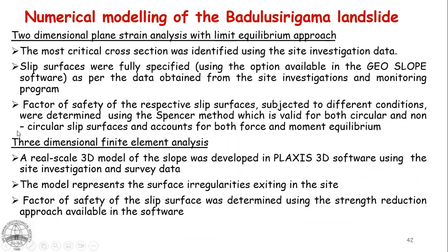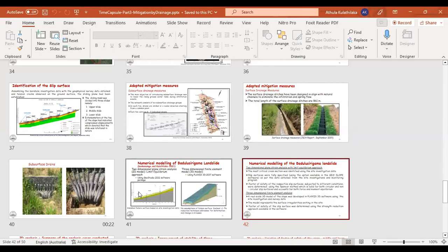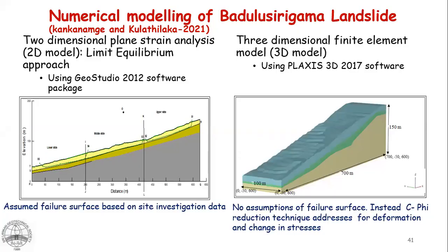Now this process was numerically simulated later with detailed research. We did a 2-dimensional analysis, modeling the infiltration and the subsurface drains with SEEP/W software, and SLOPE/W software was used to analyze the stability. Also, we did another analysis with Plaxis 3D software.